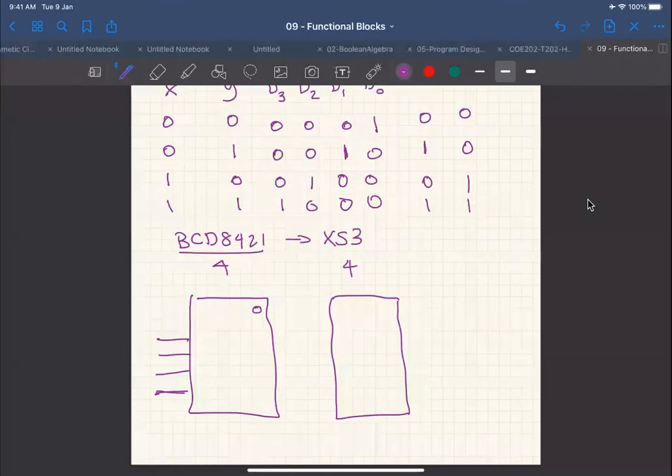When we get a 0 here, I want this encoder to output 3, right? I connect this D0 to D3 instead. And D1, when I have 1, I want my output to be 4, so I connect it to D4, until I reach, let's say, D8 and D9.